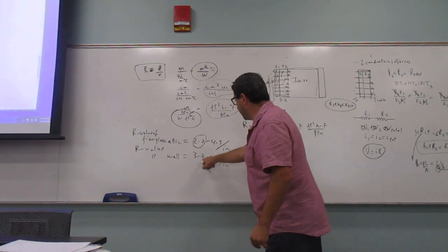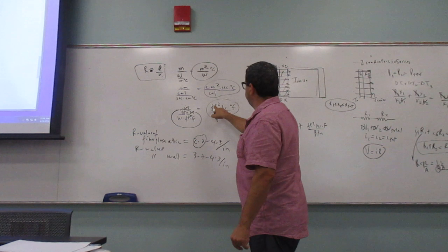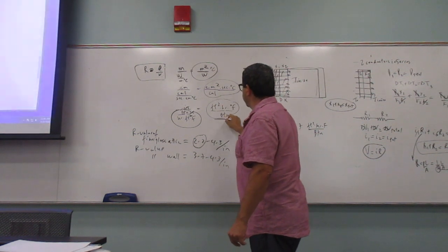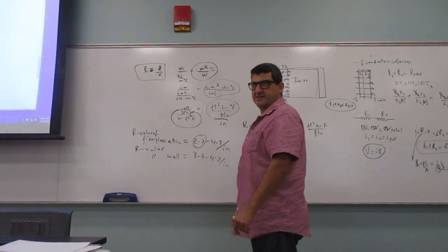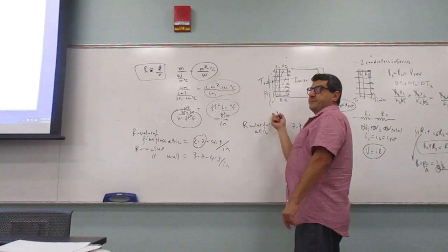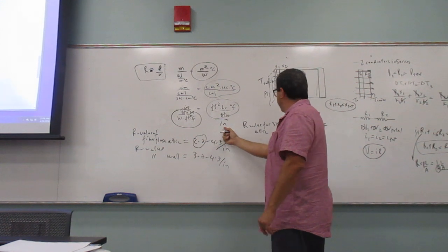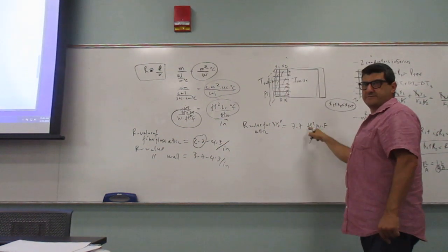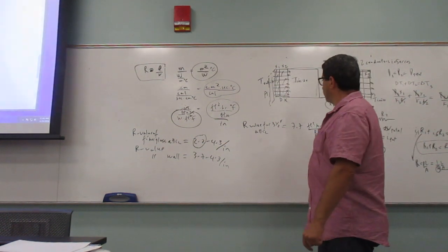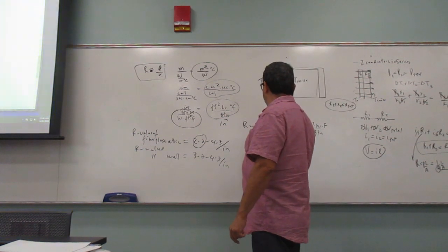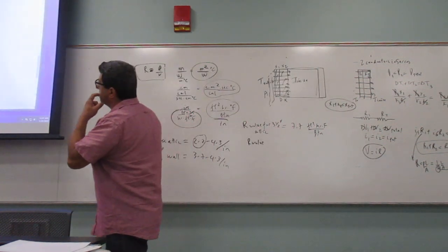But the units of this guy, 2.2, is feet squared hour Fahrenheit over BTU per inch. You see? Then, depending on how many inches thickness it is, you have to multiply it by inches to cancel that, and then you get the units of the R. You see? So the R value, let's see if that's what they put.